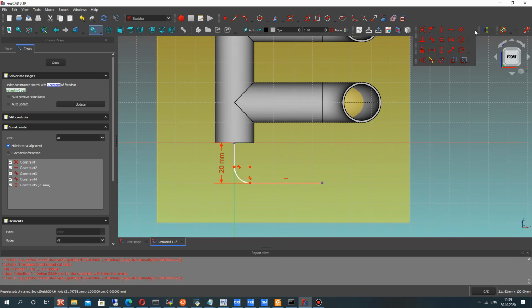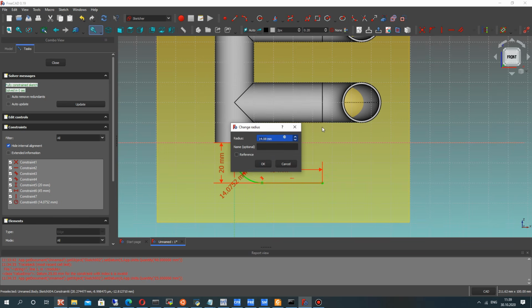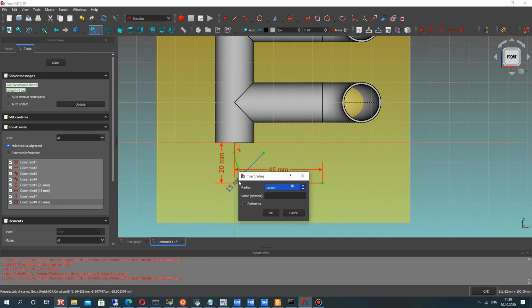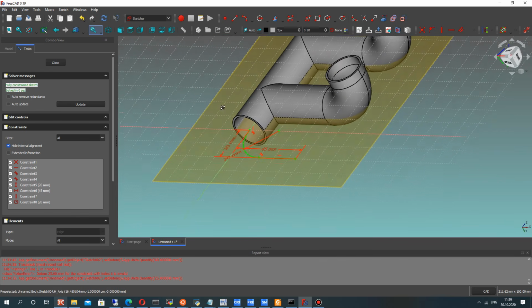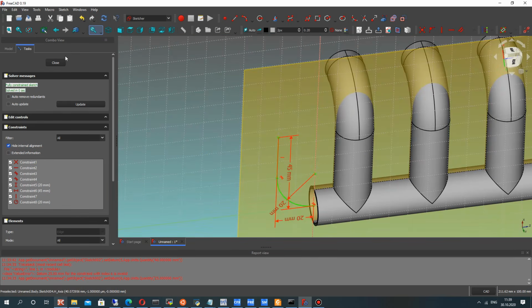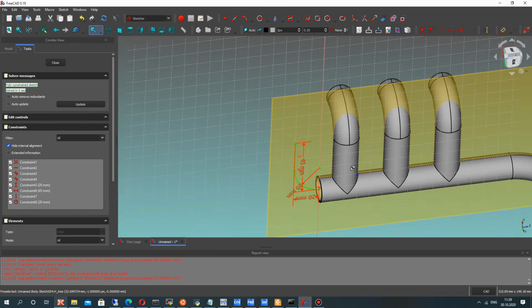For faster creation of the sketch, we have to create the topology, and after that set the dimensions, because if we delete the topologies, it will delete the dimensions. It will be very long if we repeat the creation of dimensions, of course. Okay, let's close the sketch.